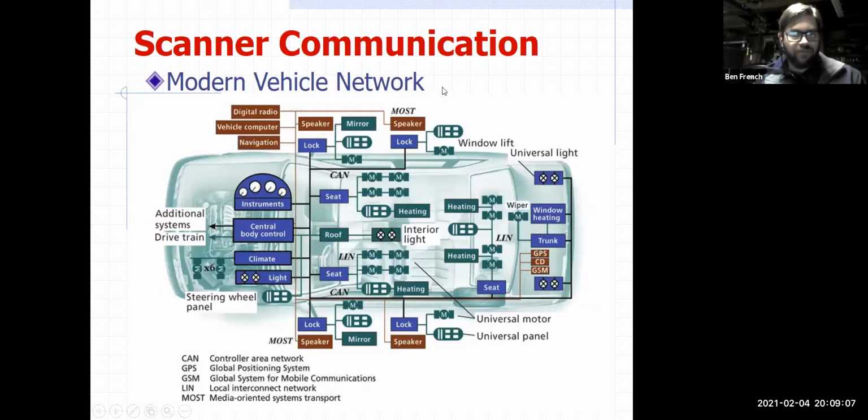We talked about vehicle networks a couple weeks ago, and I said modern vehicles are very much networked, and you can have weird things take stuff down, right? I gave you my example where I was working on a Corvette, and the driver's side power window switch was preventing the car from starting. Why? Because that's not just a window switch. That was a module, a computer on the network, and it was bringing down this network.